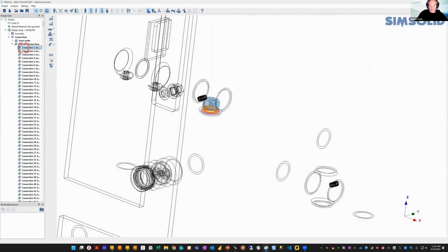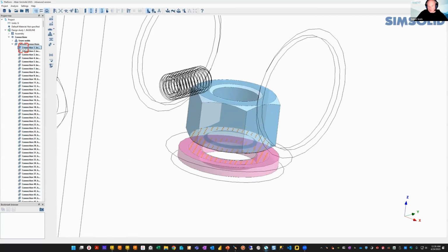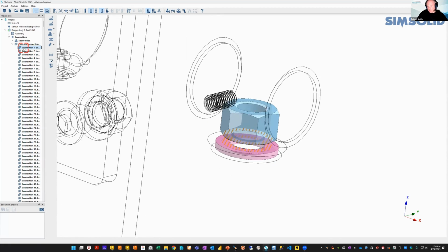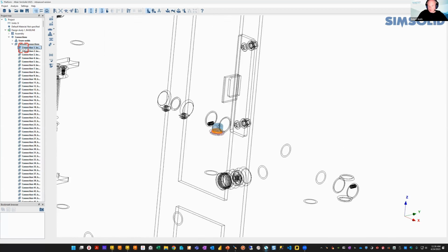And the reason for that is number one, I didn't need to, right? Even though there are interferences there and there's lots of tiny little features on the geometry that normally would be a nightmare for me, these little chamfers and things like that, no longer a concern. But it also detects that these are bolted connections based on the shape of that geometry. And I get some very specific results as a result of that.